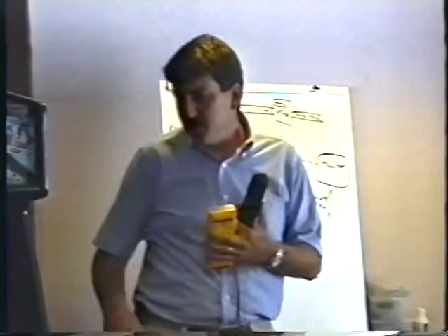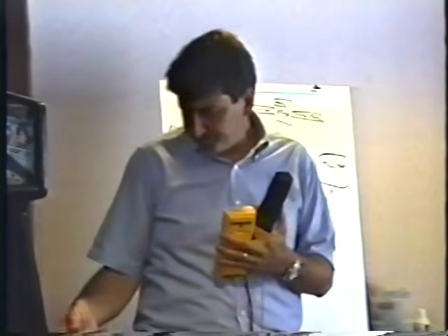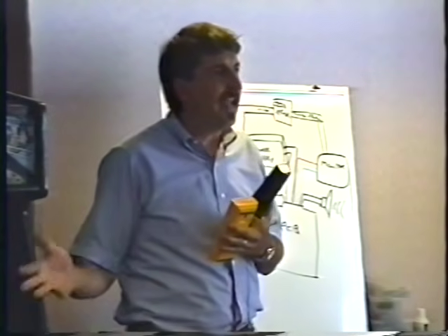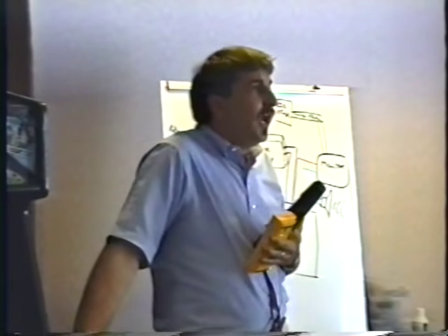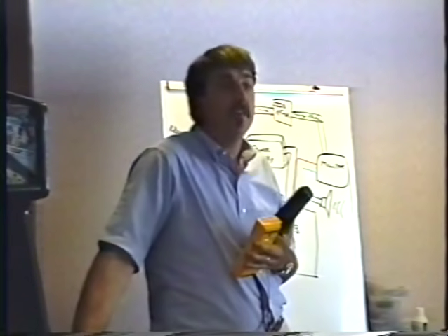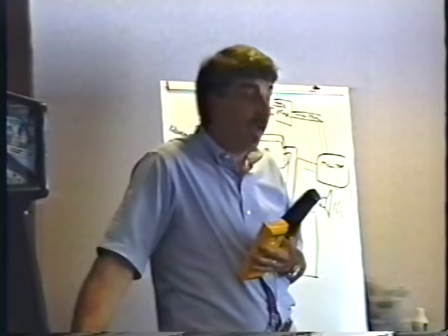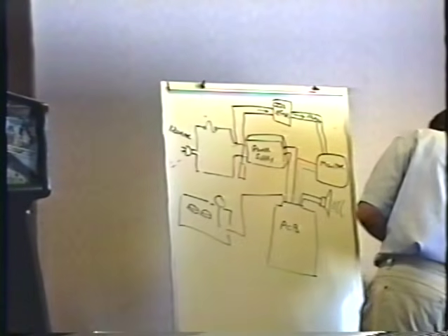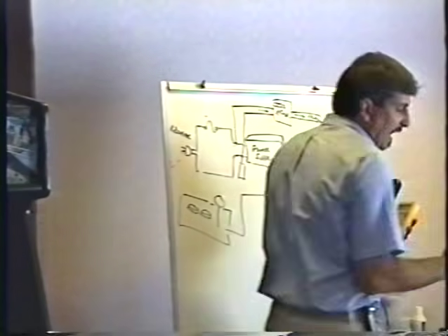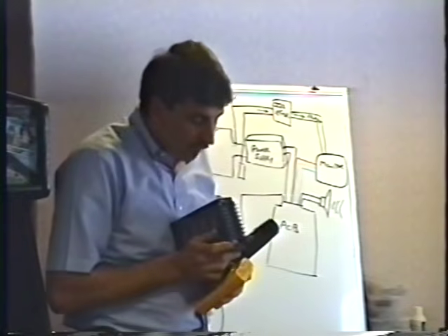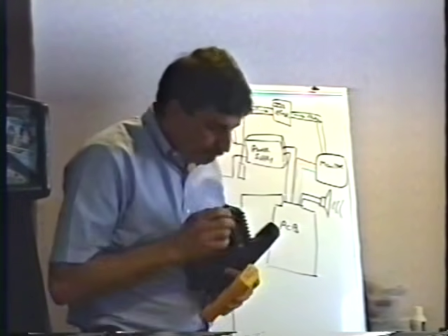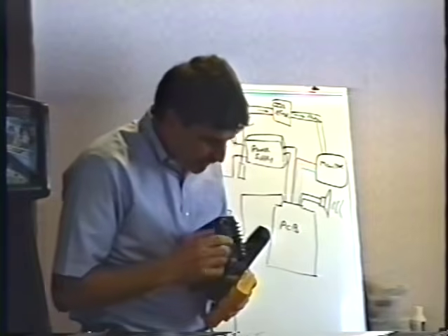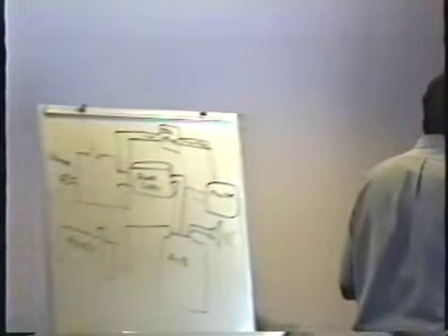So let's say you coin up the game and you don't hear any game sounds whatsoever. The next thing you want to do is check the power supply. Check to see if you have your 5 volts. Now, if you just want to check the power supply to see if it's working or not, that's pretty simple. On the power supply, you've got the screws on the side. In fact, let me go over here and show you up close what I'm talking about.